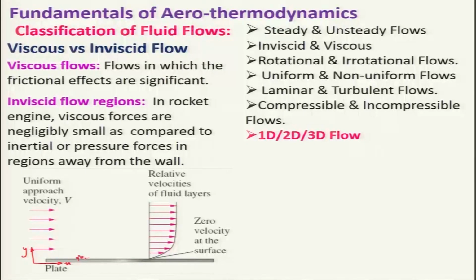Due to inertia, because this plate is fixed, and due to continuum, the velocity along the x direction will be 0 at any point on the surface of the plate, and also at the wall of this plate both the velocity along the x direction and y direction will be 0. As a result, the fluid elements will be getting dragged and resisted, and there is a viscous force which will be acting over here. As a result, the velocity will be 0 at this point, and then it will be increasing, and of course it will reach the free stream value, resulting in a velocity profile.